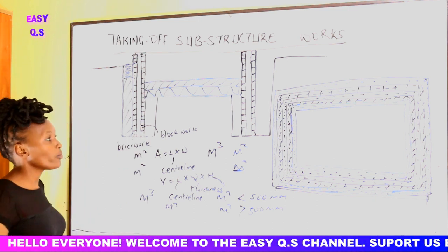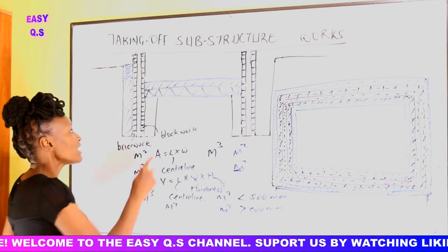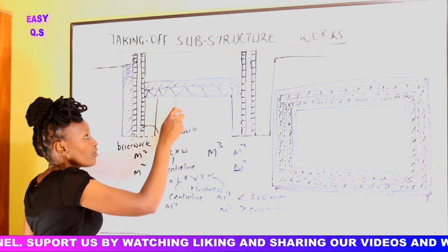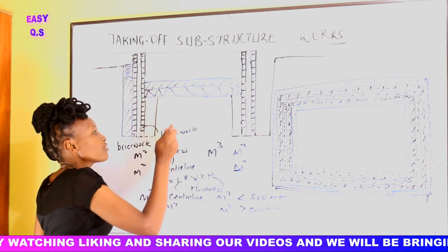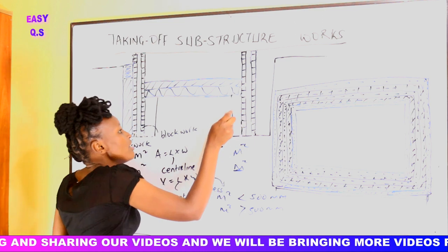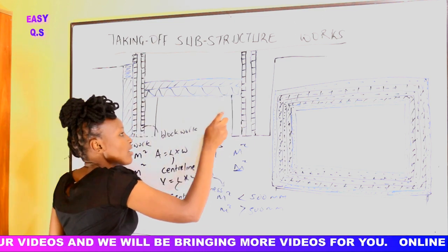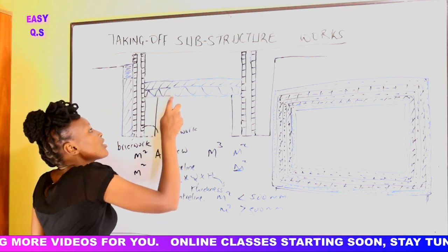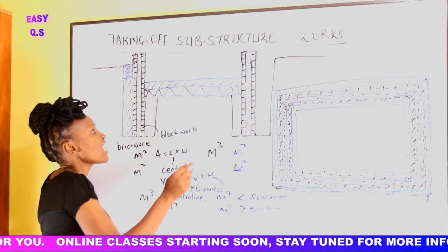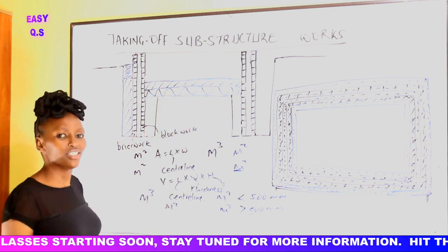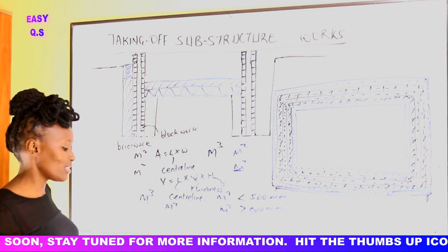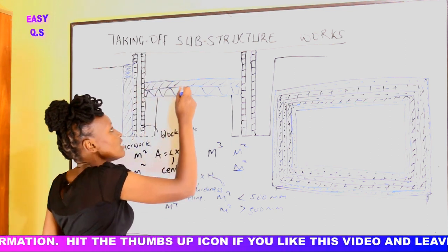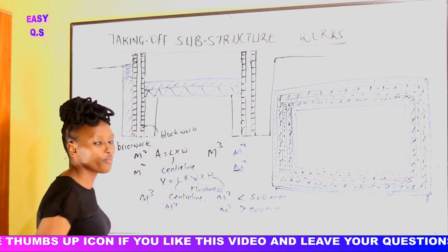So the thing that we can observe clearly is that this area where we did the hardcore, the area of the hardcore, the area for compacting, first of all we started with compacting this area. We compacted the ground inside the house, then we laid the hardcore, same area, then we compacted the hardcore filling, same area, we laid the floor insulation which is in the same area. Now we shall do the damp proof membrane on top of the insulation to prevent any moisture from coming up.